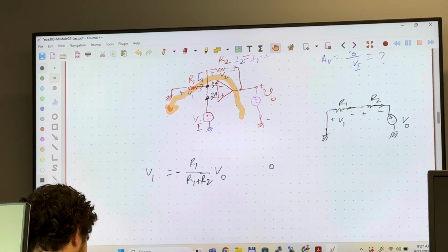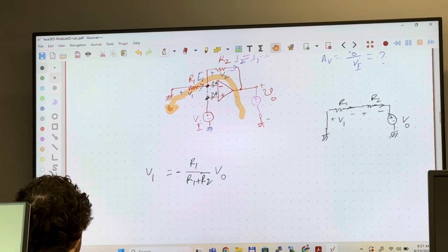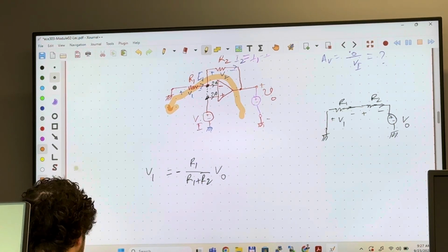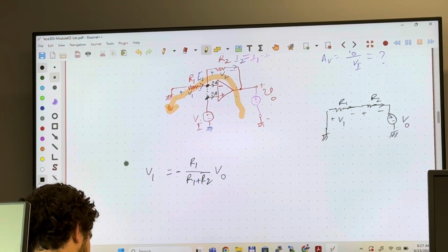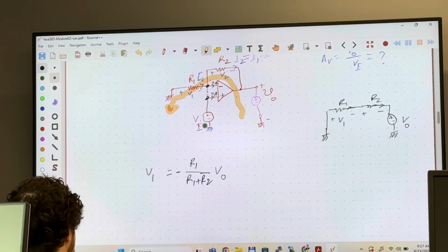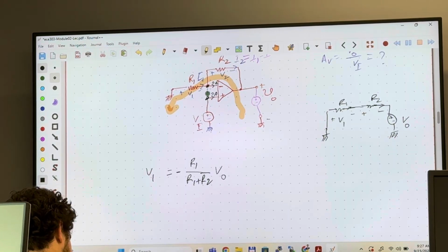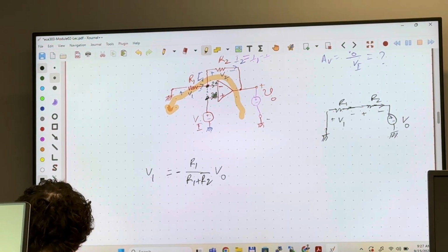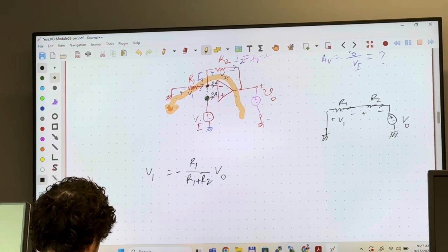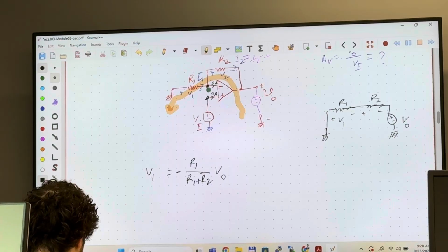Now I have another circuit. So I'm going to put different colors here. Okay, guys, do you see the input voltage here, V sub I? Positive here, negative here. I said that because of the feedback, and we said that the op amp is ideal, these two input terminals are virtually connected, short.